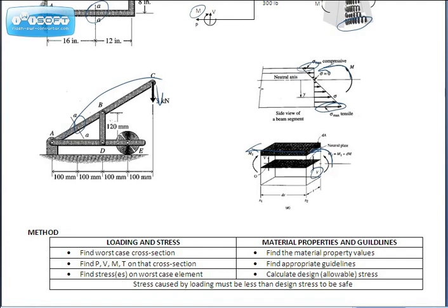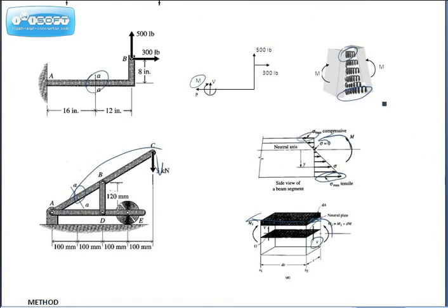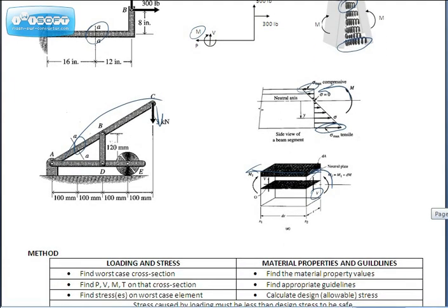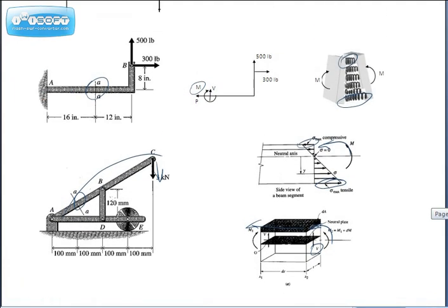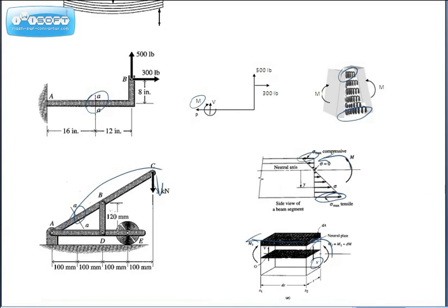So those elements inside a bending member have to respond to both the stress trying to pop them apart here and trying to compress them into themselves here, and the stress trying to slide them against each other, caused by the transverse shear V. We will not do a test on bending in this lab.